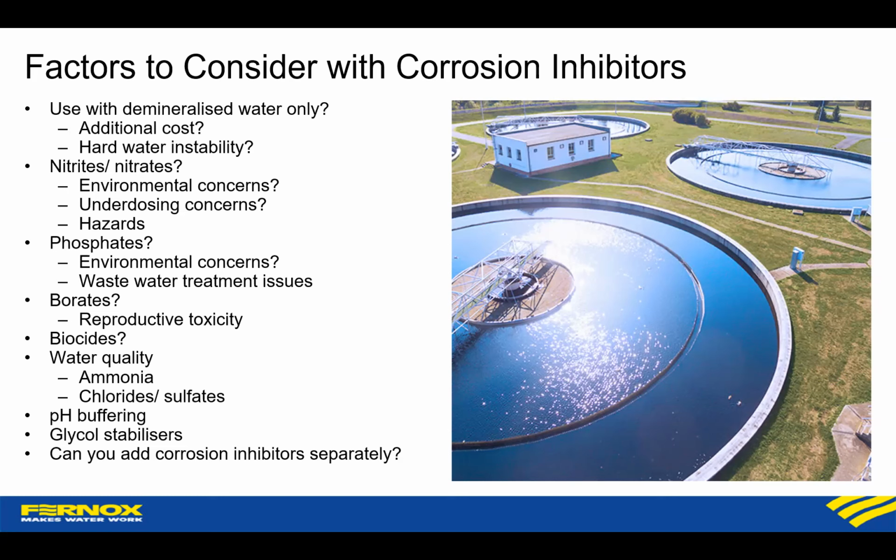Glycol stabilizers, occasionally if you've got a good source of maybe glycol or some other heat transfer fluid, a cheap source, and you don't want to buy a formulated product, that's an option certainly, but just be aware that a formulated product may have things like stabilizers in to protect the glycol from degrading, going yellow and losing that frost protection. And linked to that, can you buy the corrosion inhibitors separately?